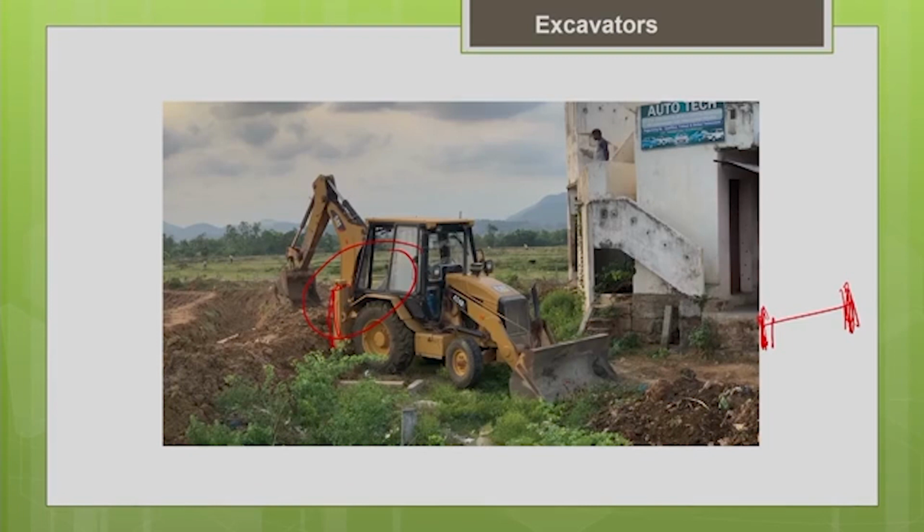So when the backhoe is doing the excavation job, you extend the outriggers completely and transfer the load to the ground through the outrigger, instead of the wheels. This will ensure the stability of the machine when it is doing the excavation. Now you can see this video of how the trenching operation is done with this loader backhoe combination.